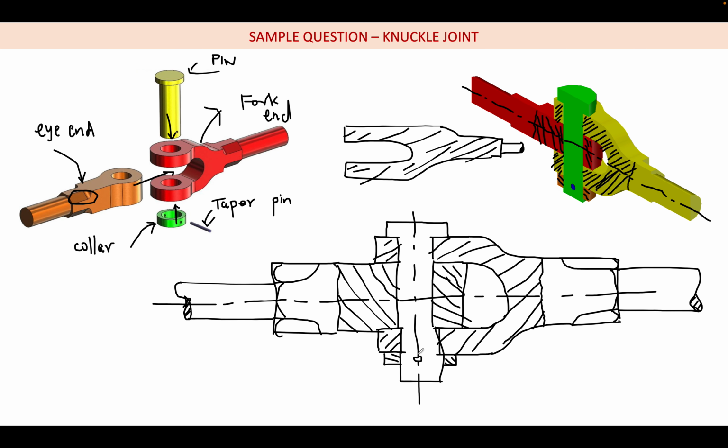The small part, is it whether the same shaft which I showed you is applicable to the pin also, or not? The pin is a different convention. So we saw that for the pin, when it passes through this, we are not sectioning. But here it is cutting the cross section. So whether we have to follow what is followed for the shaft, or should we avoid the sectioning? That is the question.